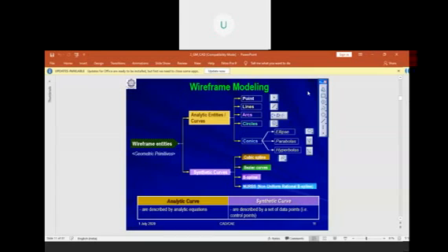For example, you already know from your mathematics class the equation of a line, the equation of an arc, how to represent a point, the equation of a circle, the equation of different conic sections. There are different types of representation. But a synthetic curve is described by a set of data points, also known as control points. It is also mathematics inside, but the description is based on a set of data points. The different synthetic curves are the cubic spline, Bezier curve, B-spline curve, and there is a concept called knots.